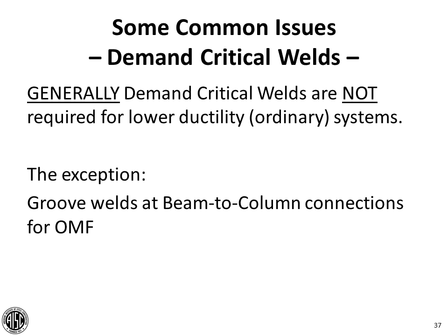It's nice when you can sort of pigeonhole things pretty easily. So if you have a high ductility system, you need demand critical welds. If you have a lower ductility system, you don't. In this case, there is an exception. When we're talking about the groove welds at beam to column connections, even if you have an ordinary moment frame, those welds are still going to be required to be demand critical, and the demand critical requirements are laid out in AWS D1.8.